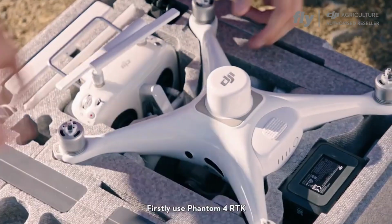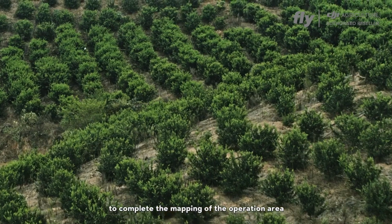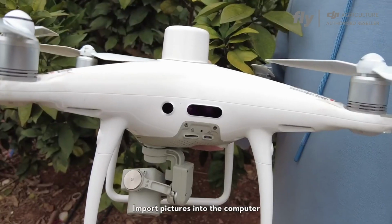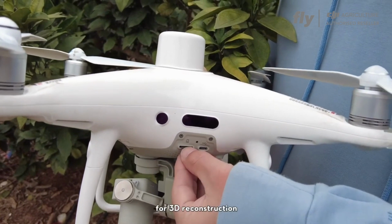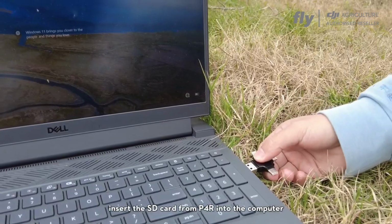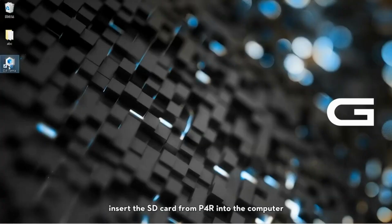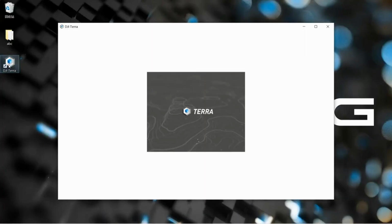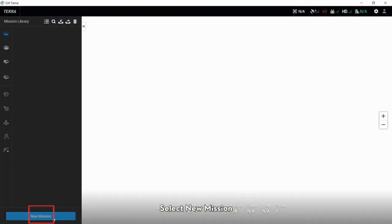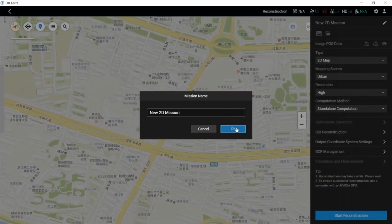Mapping. Firstly, use Phantom 4 RTK to complete the mapping of the operation area. Import pictures into the computer for 3D reconstruction. After mapping, insert the SD card from Phantom 4 RTK into the computer. Open DJI Terra. Select New Mission and select 2D map.